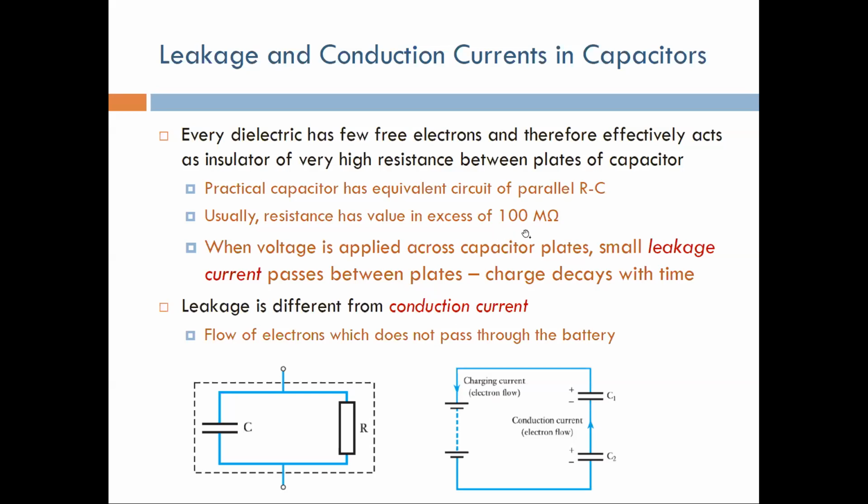But this 100 mega ohms might not be much. You can actually assume that it's infinity, but if you have this particular capacitor charged to 100 volts, for example, this 100 volts will discharge very slowly through this resistance.